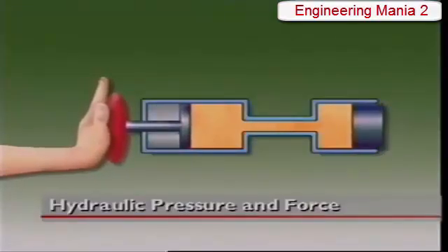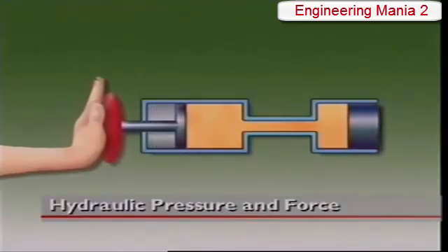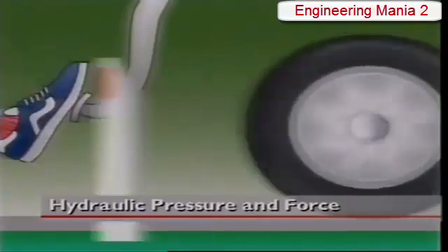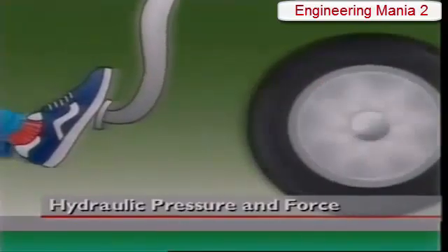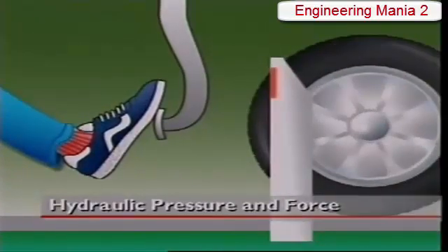Hydraulic pressure is transmitted through liquid. Since liquid is effectively incompressible, pressure applied to a liquid is transmitted without loss throughout the liquid. In a braking system, this allows a force applied to the brake pedal to act upon the brakes at the wheels.